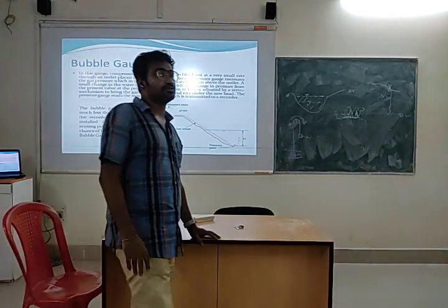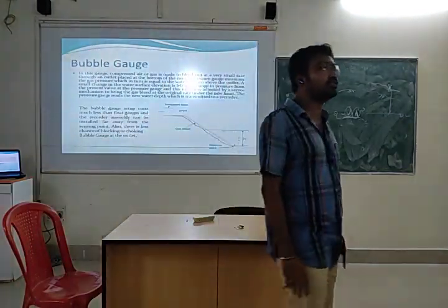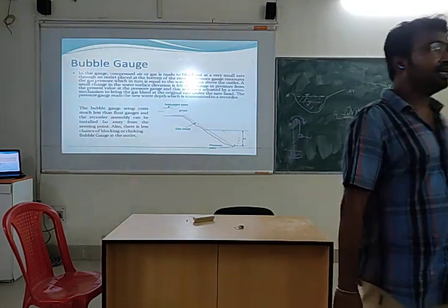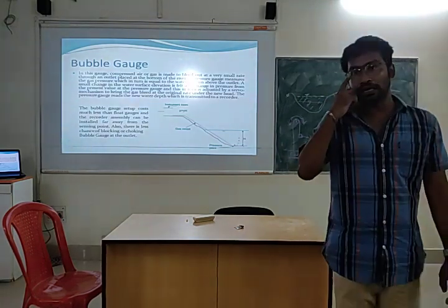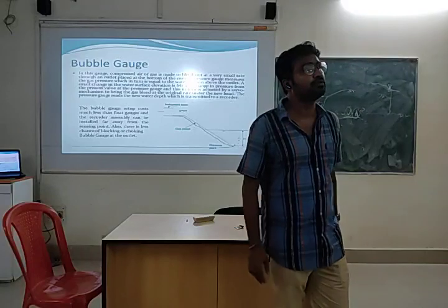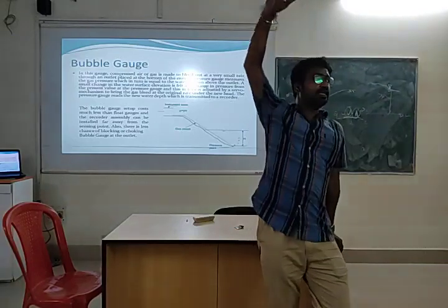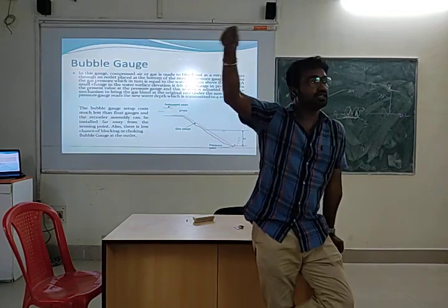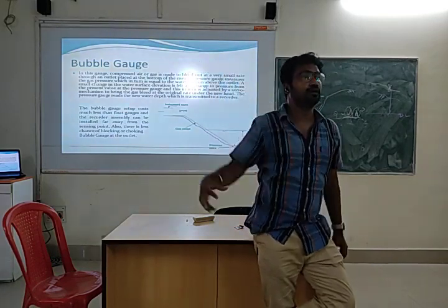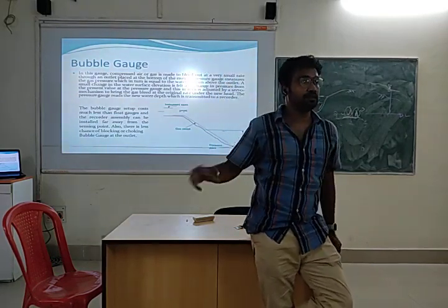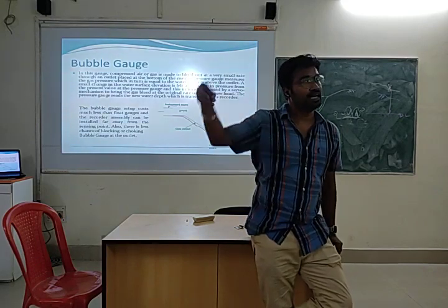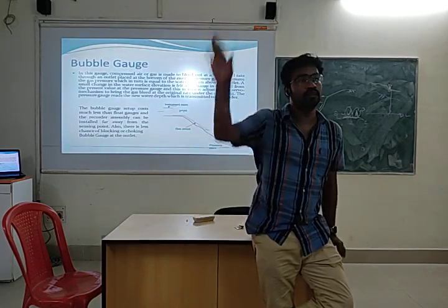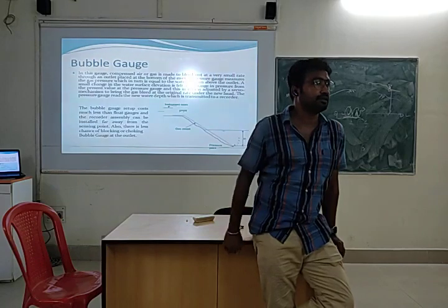Why are you recording this? To find out the discharge only. Otherwise, what will happen if we try to find out the discharges? We will go to the stream, and we will lower some type of tape. At the end, we will fix some sort of weight, and we will lower it down, and we will measure the length or elevation, right?